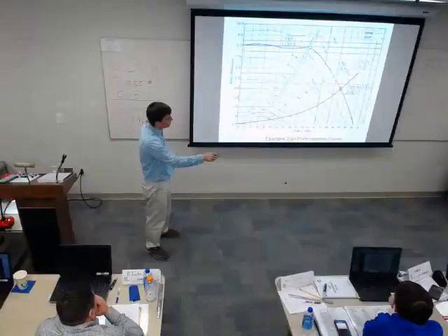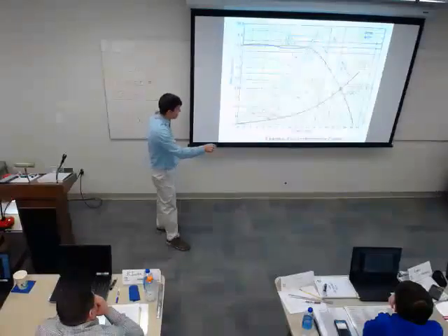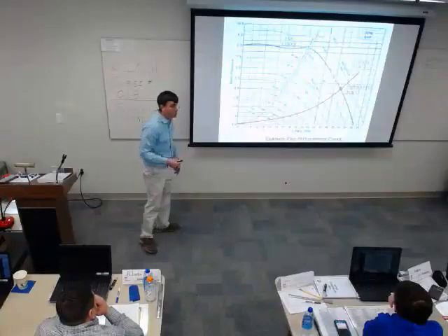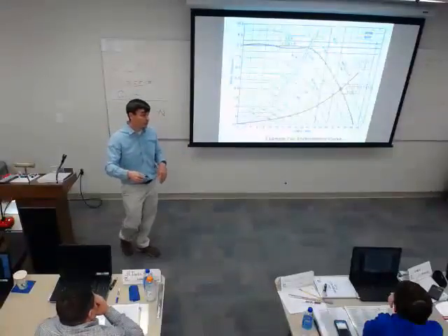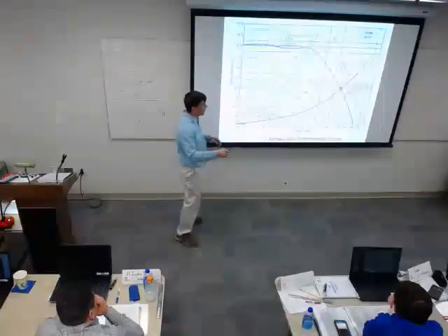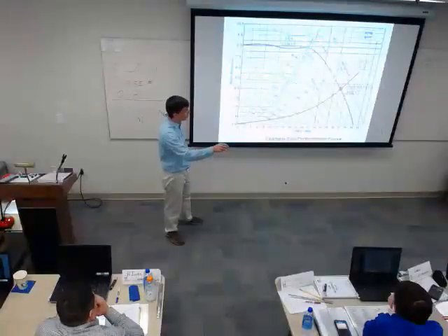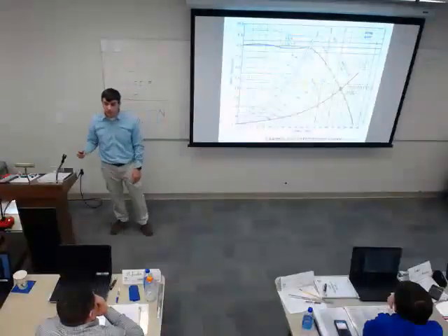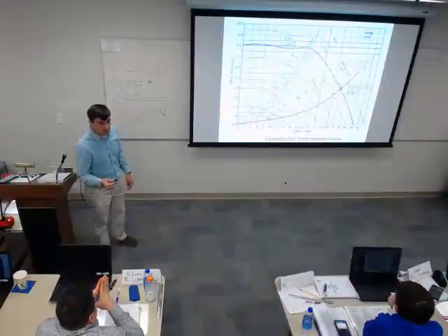It's called riding up the curve. My system curve would then be wherever that intersection was. I have a new system curve because I changed the physical characteristics of it. In the same way, I can slide down my fan curve. If I have less resistance somehow, I'm going to go down that curve and increase airflow. Make sense? Questions?